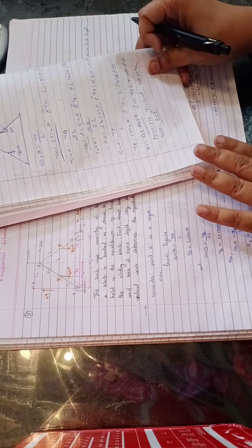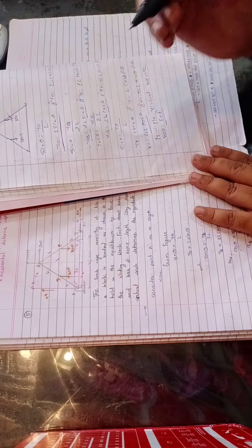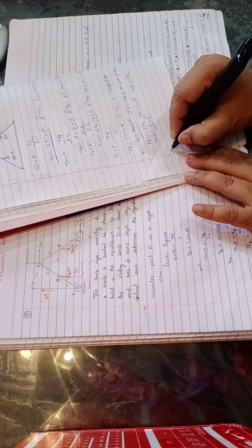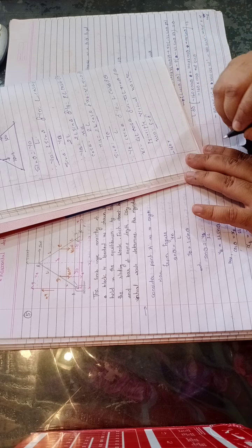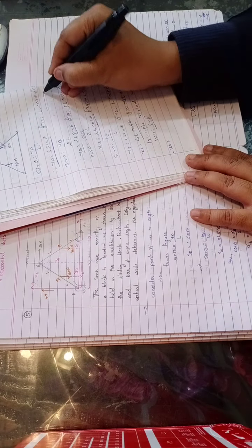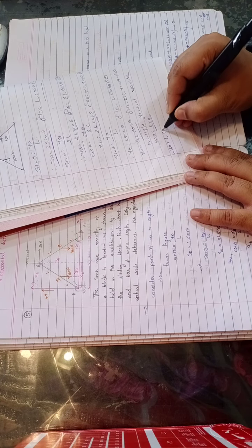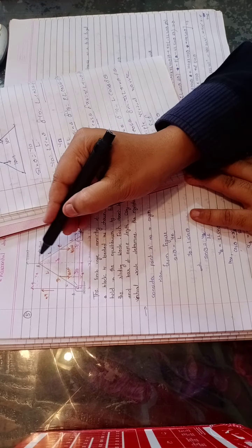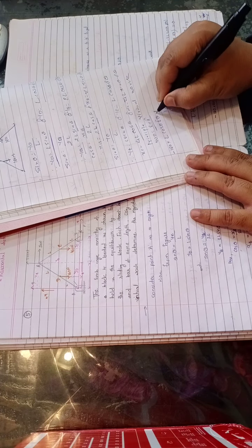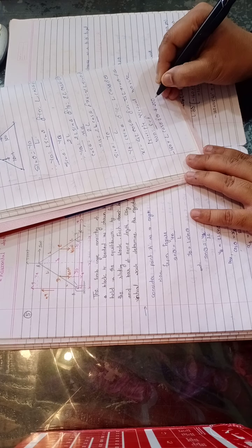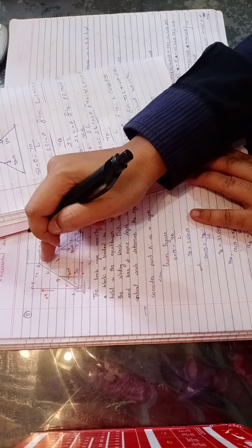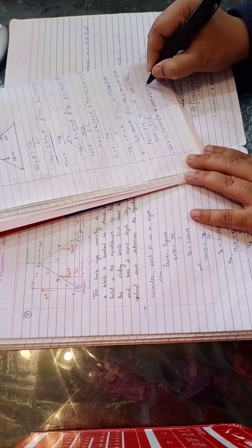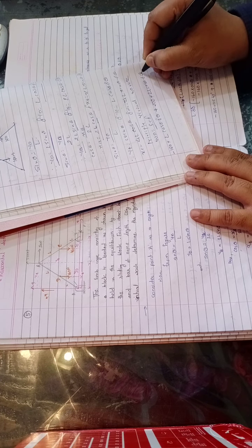Now let us see the first force, 160. It is vertically downward, so we write minus 160 multiplied by the displacement at YD, which is L cos theta into delta theta. Next, the 200 force is vertically upward, so we write plus 200, and its displacement delta YB is 2L cos theta into delta theta.